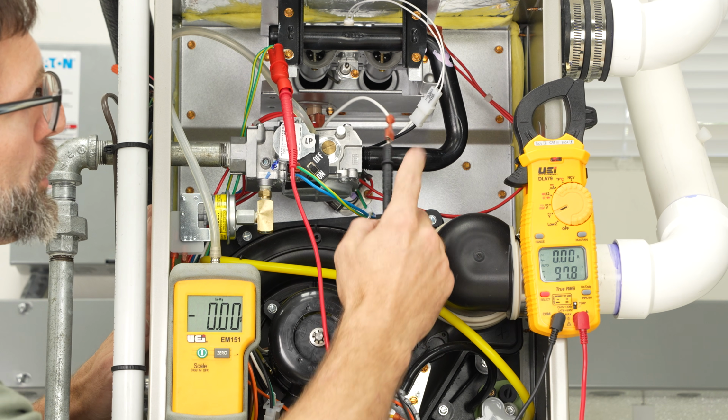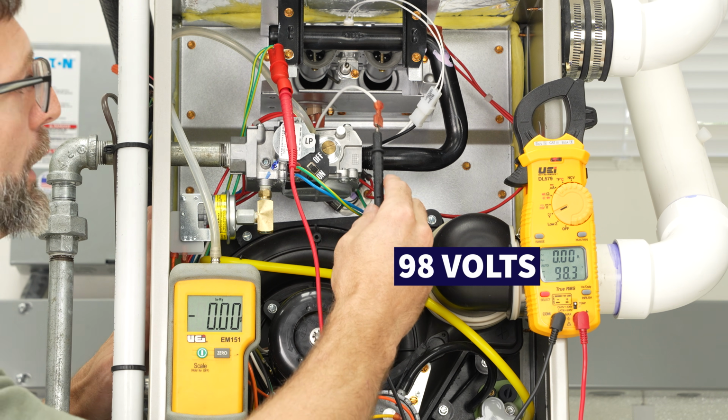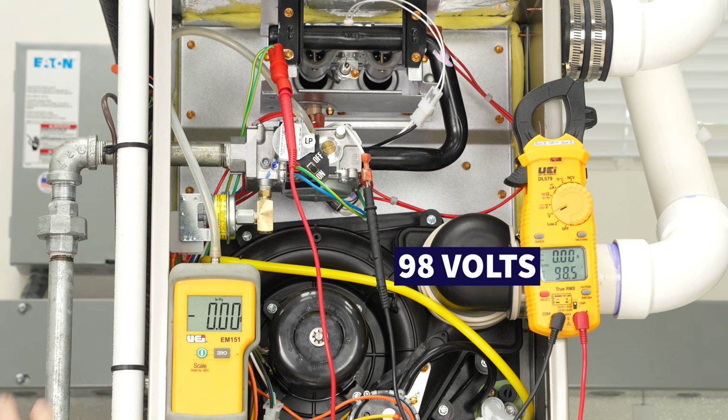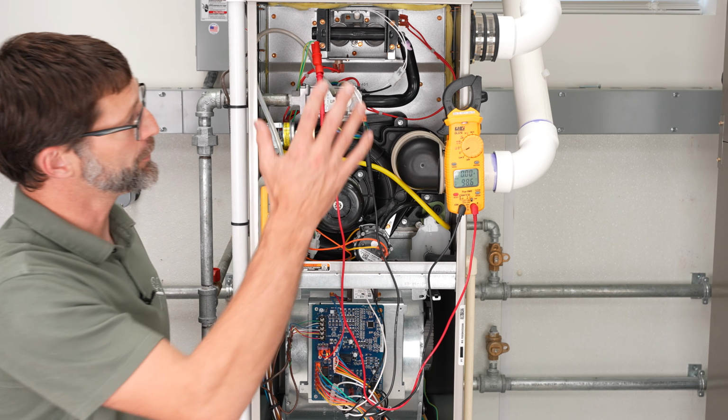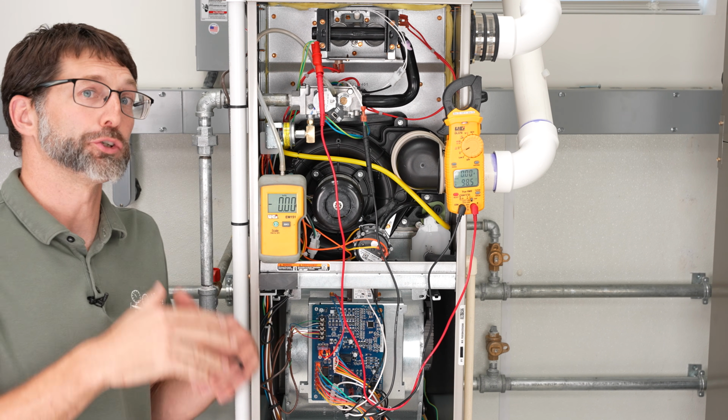So on this wire, which connects to the flame rod, we're measuring, say, 98 volts. And so it's always going to be live anytime there's power on to the furnace. So that's just a safety to make sure that there is no flame up here when there should not be.